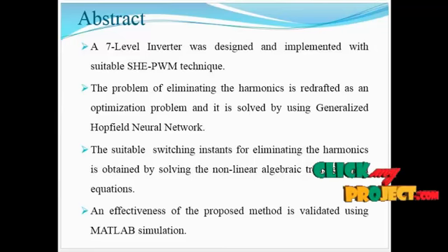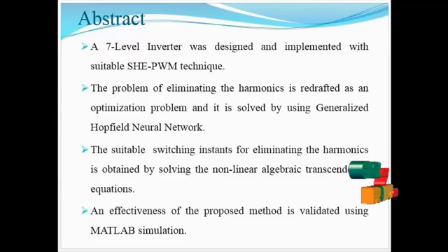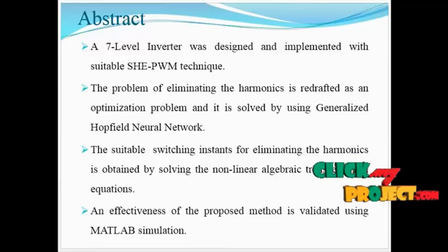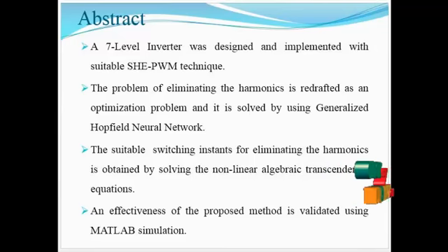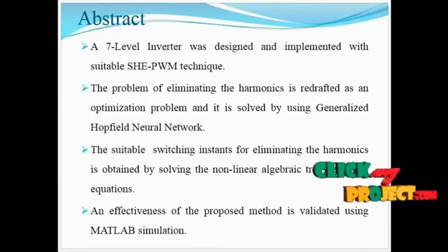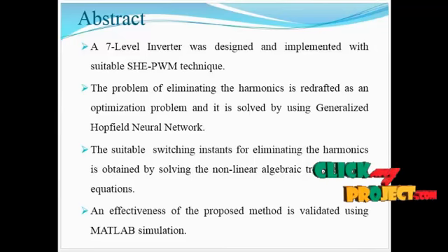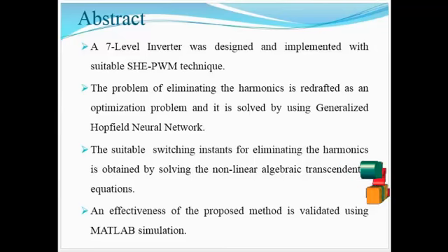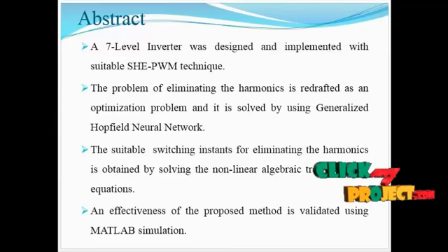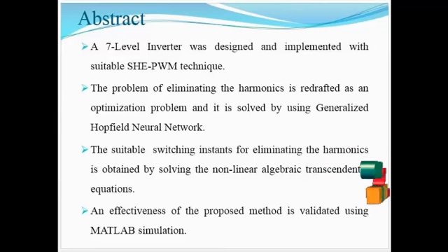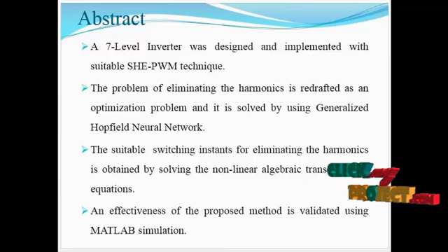This paper presents two techniques for improving the quality of output voltage and efficiency. That is, the real-time implementation of PWM, the selective harmonic elimination pulse width modulation technique in a single-phase inverter, is proposed. The disadvantages are that the level of output voltage depends upon the number of DC sources, and several carrier signals are used.